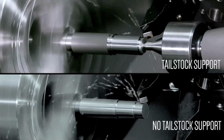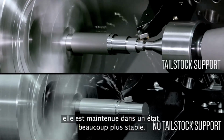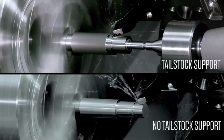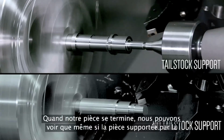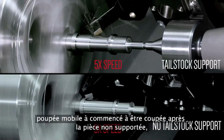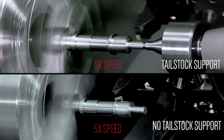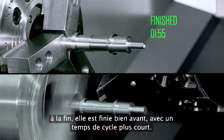The tailstock supported part is able to run considerably faster since it is held in a much more rigid state. As our part reaches completion, we can see that even though the tailstock supported part started cutting after the unsupported part, in the end, it finished well ahead with a lower cycle time.